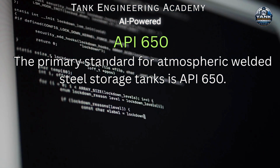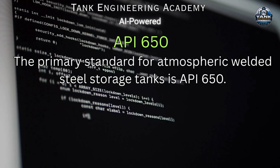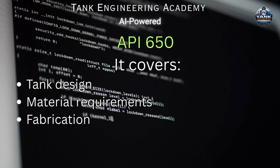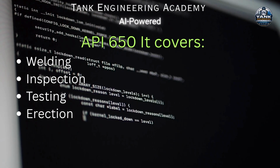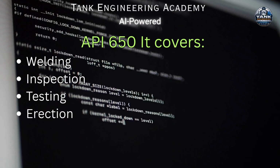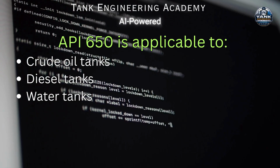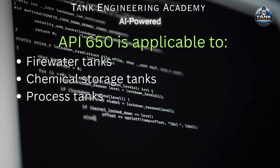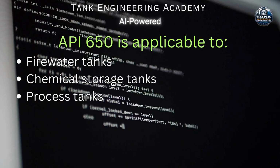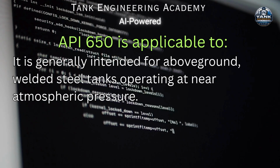API 650. The primary standard for atmospheric welded steel storage tanks is API 650. It covers tank design, material requirements, fabrication, welding, inspection, testing, erection. API 650 is applicable to crude oil tanks, diesel tanks, water tanks, firewater tanks, chemical storage tanks, process tanks. It is generally intended for above-ground, welded steel tanks operating at near atmospheric pressure.